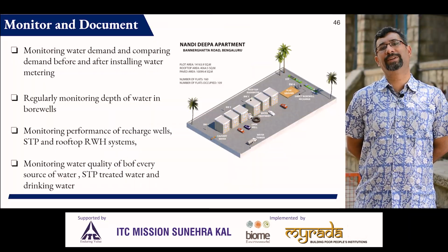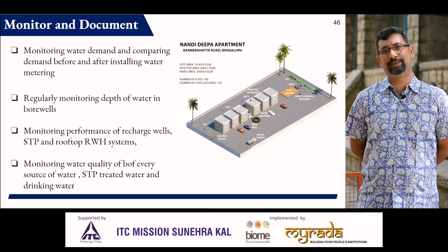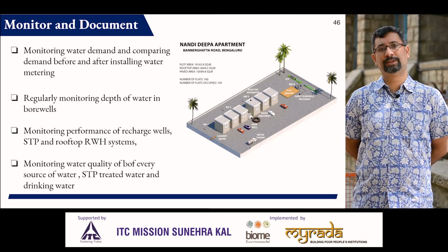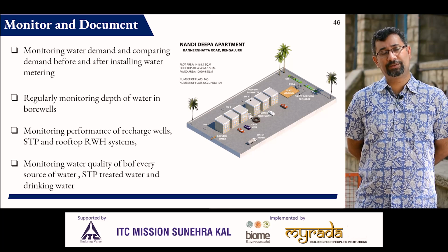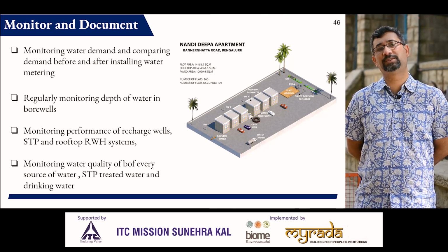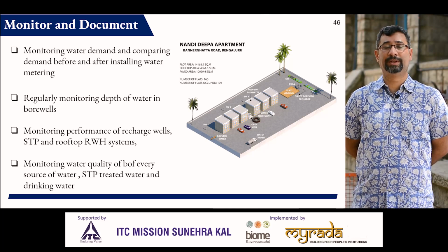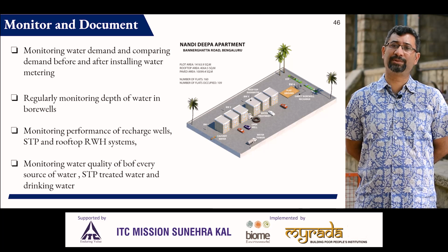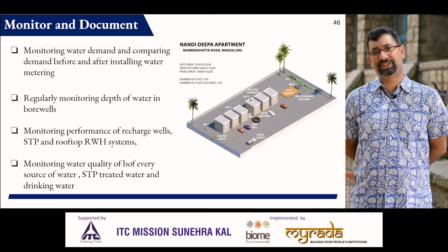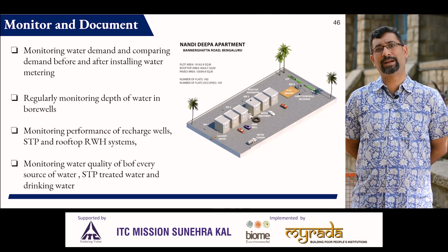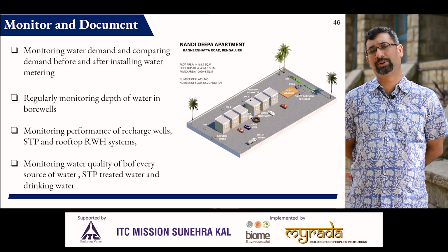It's very important to constantly monitor the yield of your bore wells, the depth of your wells and bore wells, or all your sources of water, and the quality of all your sources of water. It's important to monitor and document the performance of your STPs, of your recharge wells, of everything that you have in your system. Have a regular system of monitoring and documenting it.